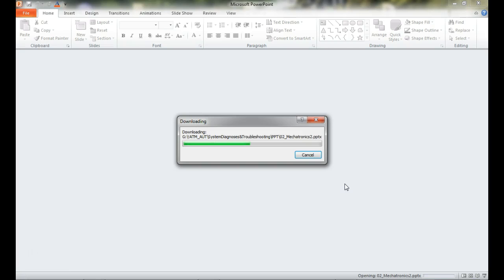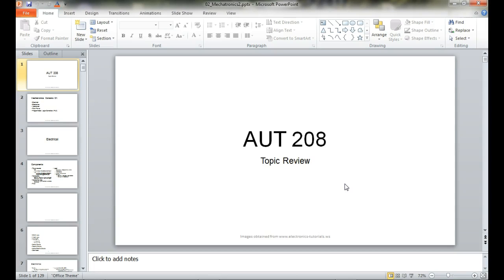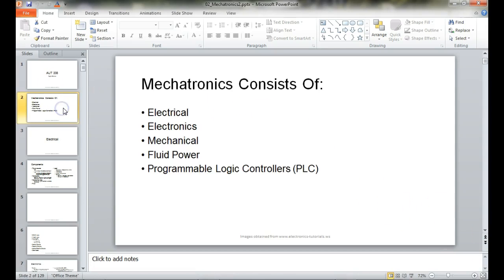An incremental encoder. So what we're doing is we were looking at position sensors, right? And we looked at a potentiometer. We went over the line and looked at what potentiometers we have over there. And we have two. The robot on the right on the Amatrol line, the gantry robot, the one on top, has a linear potentiometer, so it's not rotary, it's linear. And the one on the Festo line has one on the testing station, because all it's doing is checking to make sure the thing's at the right height.